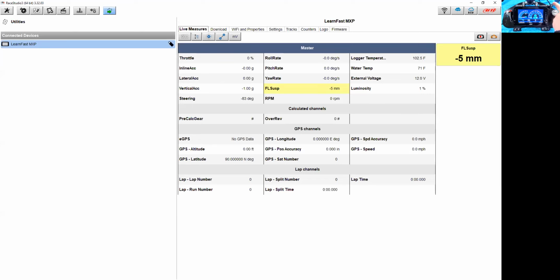I took a 200 millimeter linear pot like we have here for our shock sensor, and I was working with a Formula Continental team. They were a tube frame chassis, and we were putting stiffer and stiffer rear springs on it, trying to get the thing to do what we wanted it to do, and the lap times and the driver feel did not change. So we finally put a sensor on it. The engine was actually a stressed member the way these cars were built, so we put a sensor from the top of the roll hoop right behind the driver's head down to the rear suspension member. And the car was flexing so badly, and whenever we'd put stiffer springs on, it would just flex the car more. And that linear pot was giving us that information.